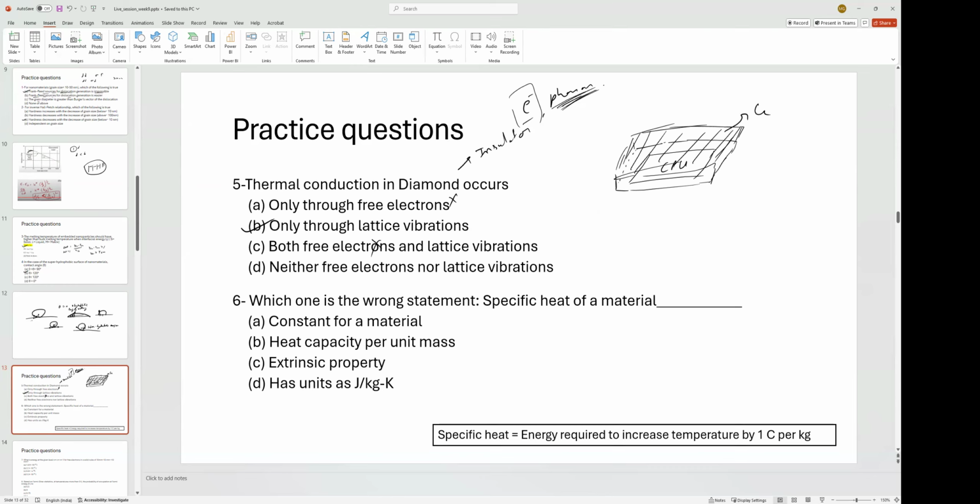At the interface, you want good thermal conductivity. If you use mechanical screws, a small air gap is left between them. You want to cover that air gap, so you use thermal gel or thermal paste to fill the void. Some of these thermal gels contain diamond, so it's insulating with very high thermal conductivity.